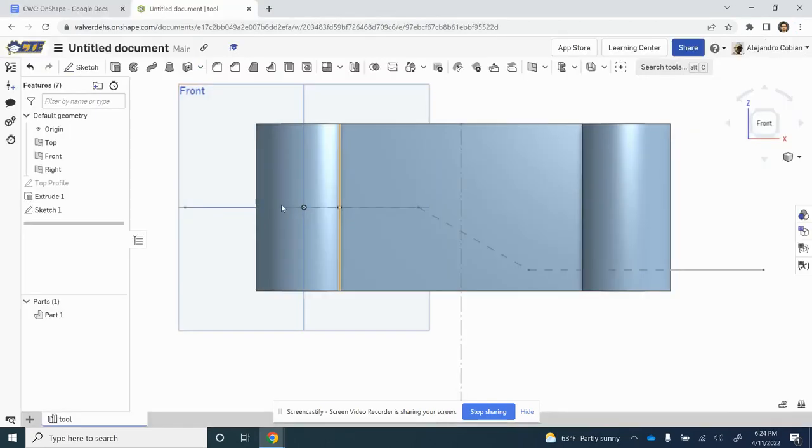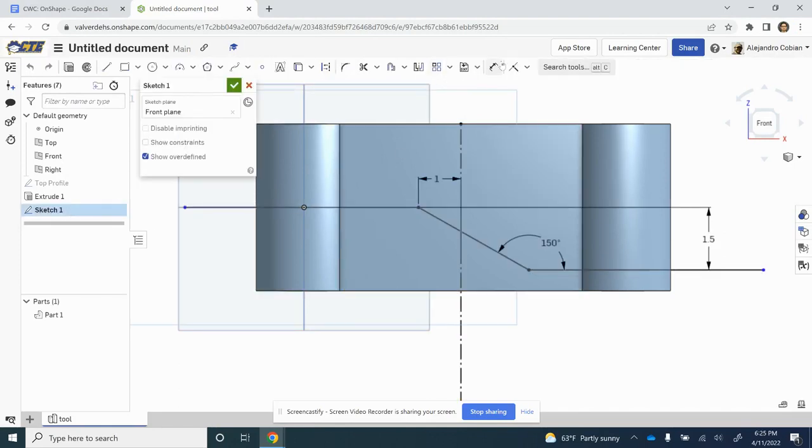So now for step 5, so that we don't do all of this work twice, we're going to go ahead and offset it. So let's go back to our sketch 1. Let's click offset. We're clicking these 3 lines. And we're going to reverse this direction and go up.